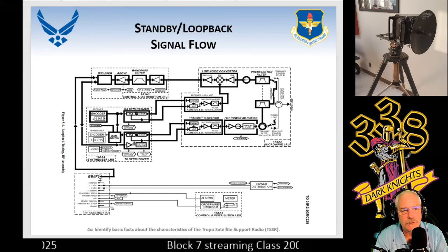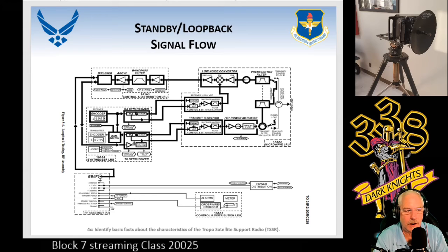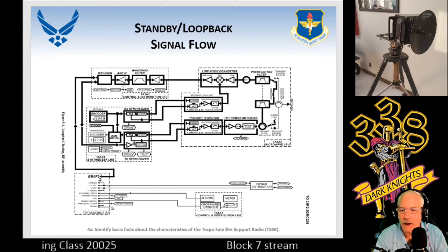So with this transmitter encoder, it is controlled by the data switch. Data switch is right next to it, and then I'm talking about the transmit synthesizer LRU, the 1A1, A4. If you look above the 1A1, A4 synthesizer LRU, past the logic, there's a transmit encoder. You'll see the data switch is highlighted. The standby operate switch controls the data switch.